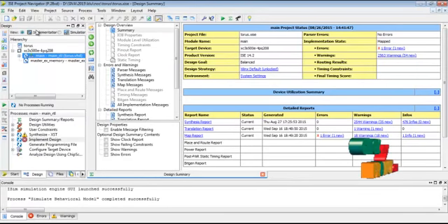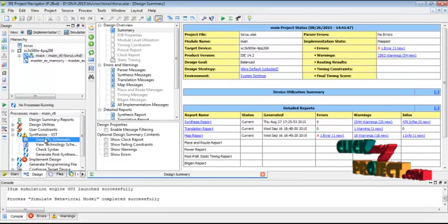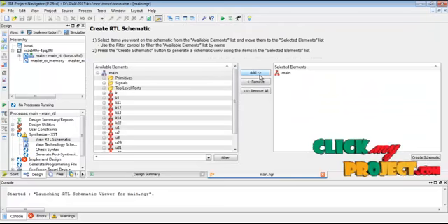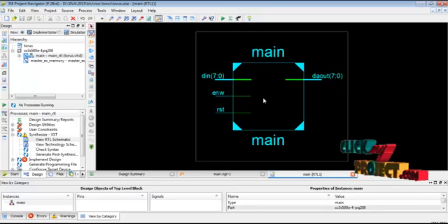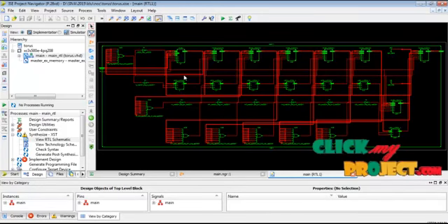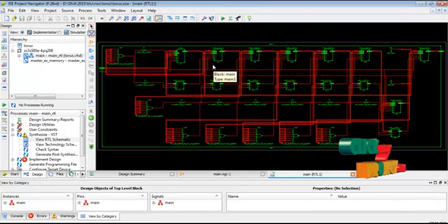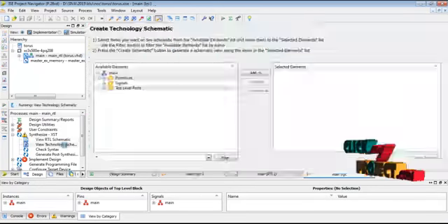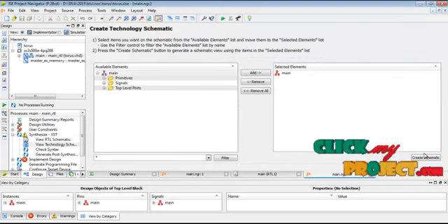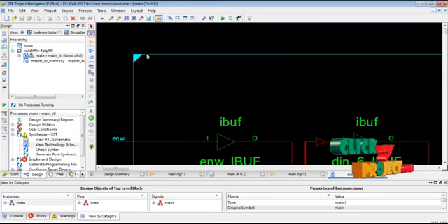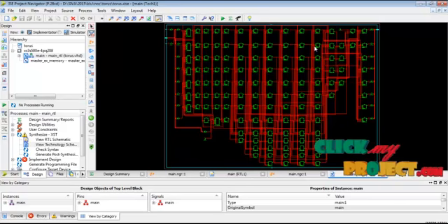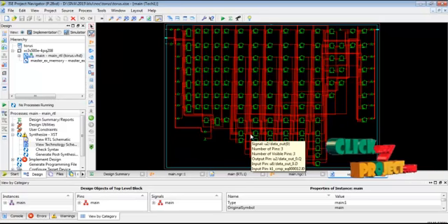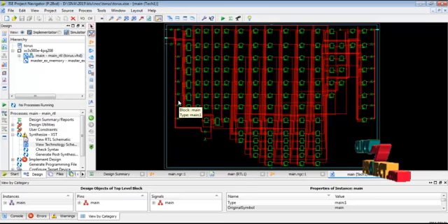Then we go to the implementation based process. The implementation process identifies the RTL diagram. The RTL diagram represents the logical blocks present in our 3D based NoC architecture design. This is our required logical diagram for the 3D NoC architecture design. Then we go to the technology diagram. The technology diagram represents the FPGA structure, a design oriented process. This shows our lookup table and flip-flop pairs, input output and buffer element connections